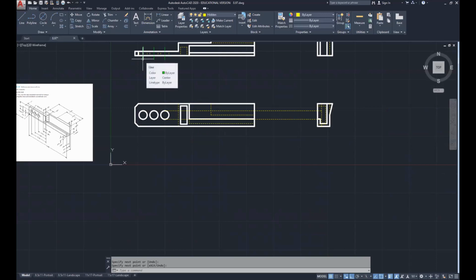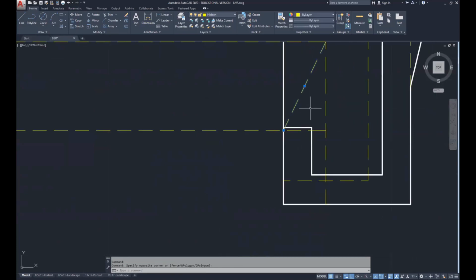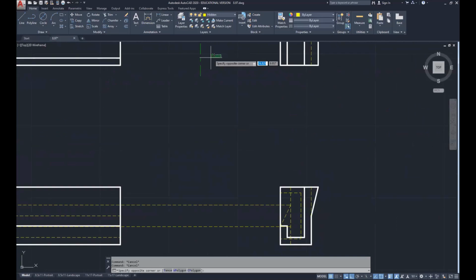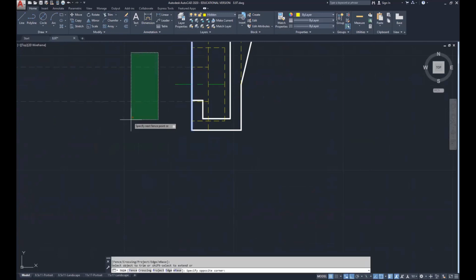I can also copy that center line, bring it across. You need a location for that, so I'm going to draw a temporary line from here to here. That's going to give me a midpoint. Take that line, I'm going to use the rotate tool, picking the midpoint, and going down. You're going to take that line, move command, go from the midpoint, and move it to that midpoint. Right click, enter, escape key, and delete this extra construction line here, and then use the trim tool to cut those two lines away.